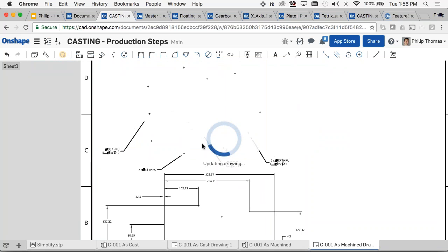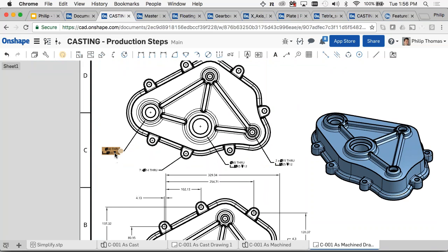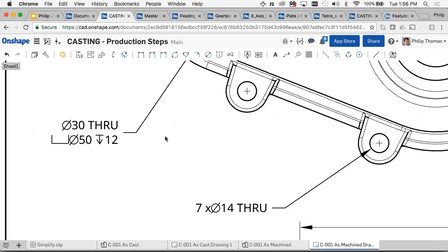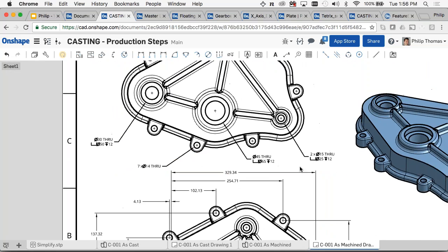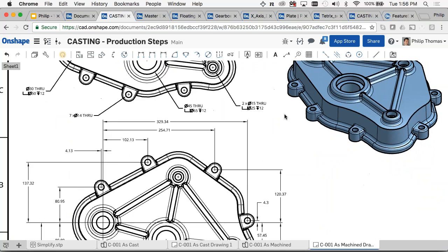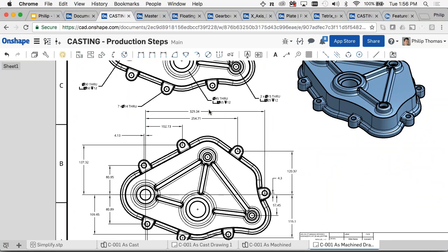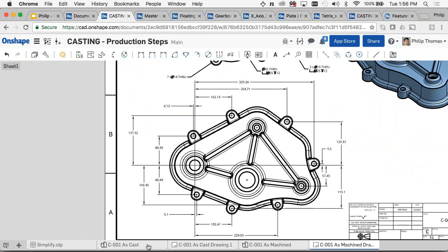And if we take a look at these views, you can see that the geometry reflects that. The 2D drawing reflects the geometry of the casting, and I've got my intelligent machined features that are automatically annotated, or rather, when I add the annotation, they are correctly and automatically annotated, and I've got my locations of the holes. How does Derived work?